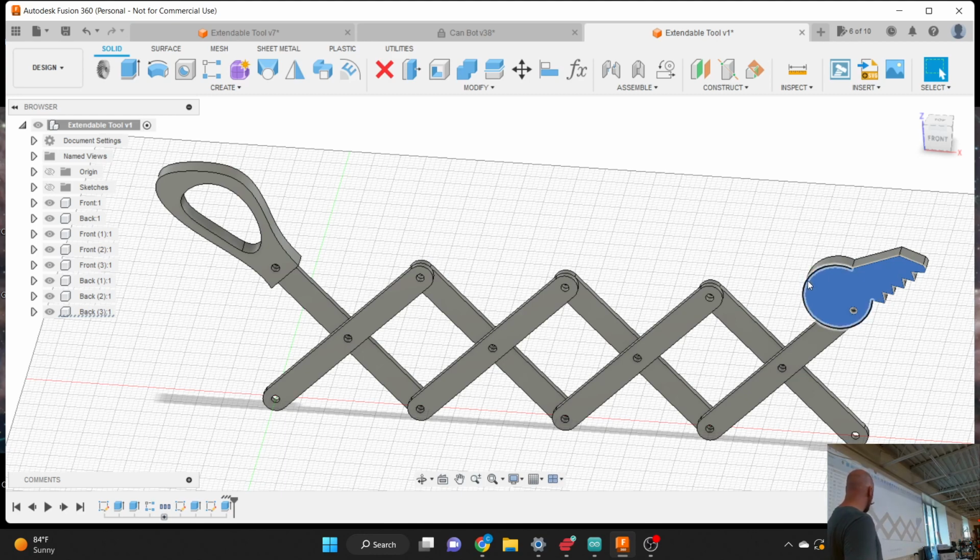start here. So we really want to be working inside of the component that we want our part to live in right now. So we have 2 components here at the end. The component that makes up this part of the scissor and the component that makes up this part of the scissor. And I want to change my active component to be the component that I want to make my parts inside of. If that makes any sense at all. English is hard. Words are hard.